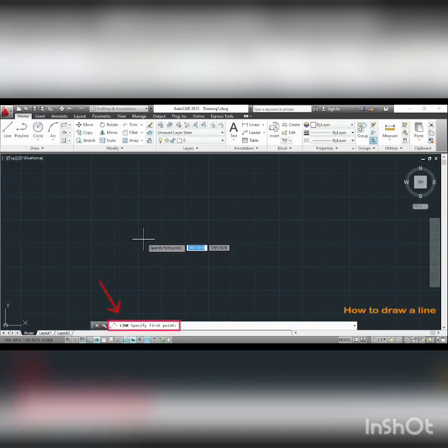If you look at the command bar, it will show that the line command is activated. Also the mouse indicator has changed. Now the small square has disappeared. And we can also find the draw tools, where we can activate the line command.